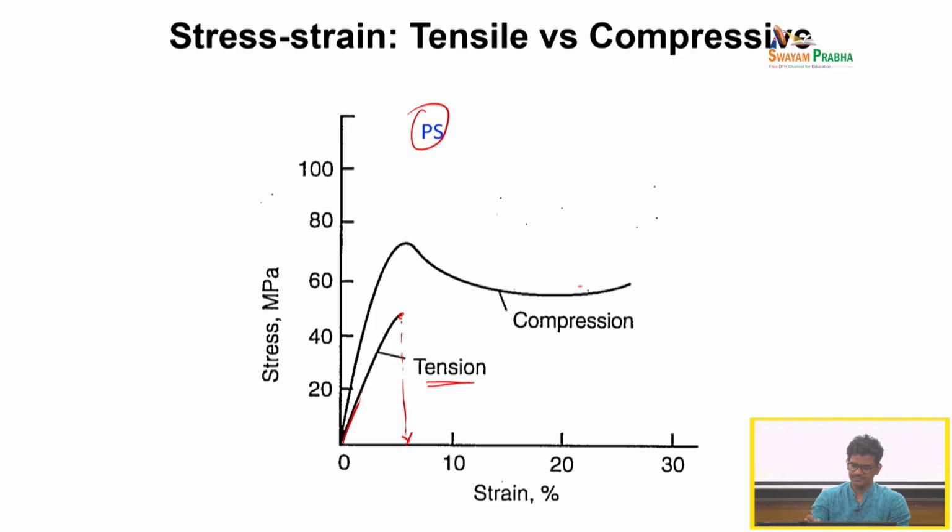So in this case you can see there is a clear evidence of a yield point here. What happens is, when you have an amorphous or glassy polymer, the molecules are not arranged in a particular periodicity. There are going to be a lot of cracks, some sort of heterogeneity. When you try to pull, you see in the video initially some small holes appear. Those holes can happen from a small defect within the material, and the tensile force basically amplifies those cracks, and it becomes easy for them to propagate and break.